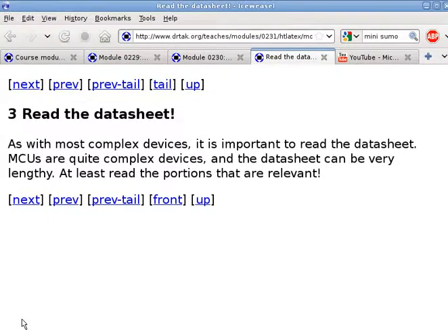So just, overall topics about designing something. Read the fine print, or read the fine manual. It's very important. Because unless you want to have smoke coming out of a circuit board, it is really important to find out the tolerances and all the specifications of the components that you plan to put onto the printed circuit board.